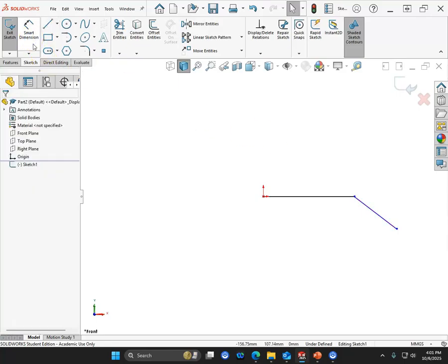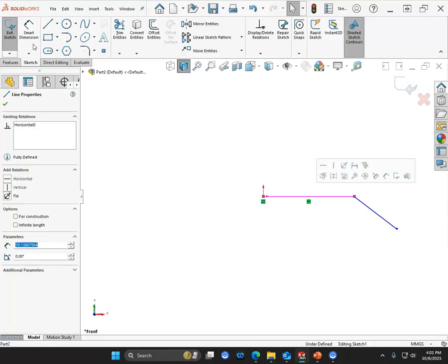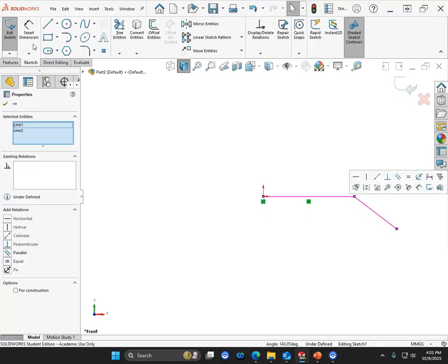We have, oh, they put that on the top. All right, well, I was going to say we could probably get that geometry in with the offset entities. So my thickness is 13 millimeters, and it will let me cap the ends, but I want lines, not arcs. We accept that, and that'll give me enough geometry that I can start adding the dimensions. So 77 to that point, and we accept. The 13 millimeters is there with the offset.